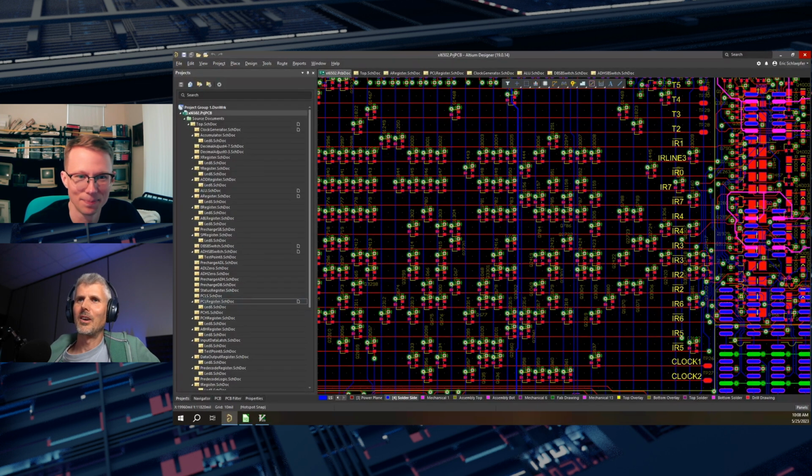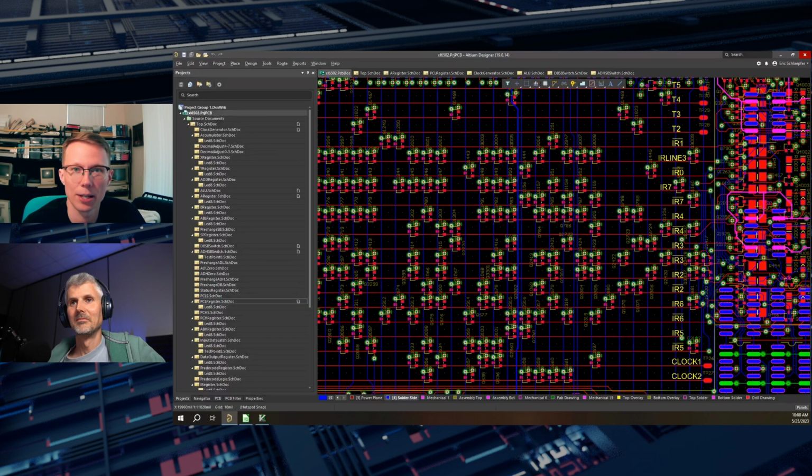Did it at that point start stepping through and clocking its first program? So the first task there was to essentially test execution of a no-op. I did that by pin strapping the data lines to the no-op instruction using resistors. The data bus is bidirectional, so I can't simply strap it to VCC or ground, because those might turn into outputs, and then I'd get excessive current.